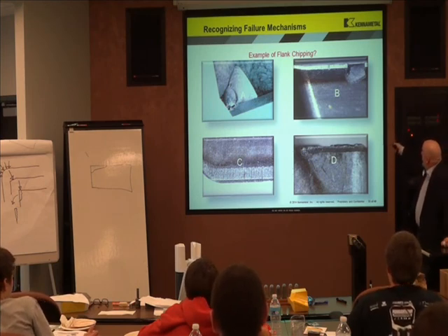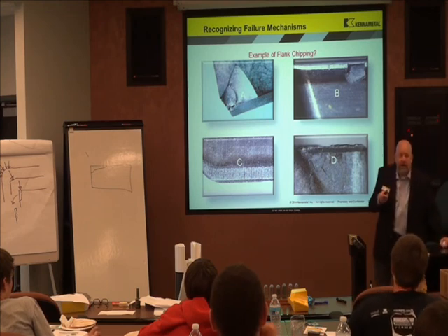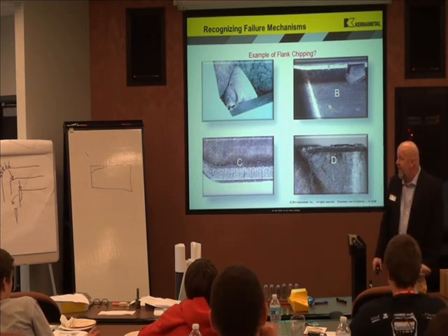You do have a little bit of flank wear here, but that's not very much. You do have thermal cracking right here. He's right though. One failure mode, if it goes unchecked, will look like something else.